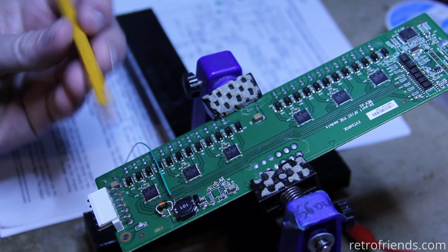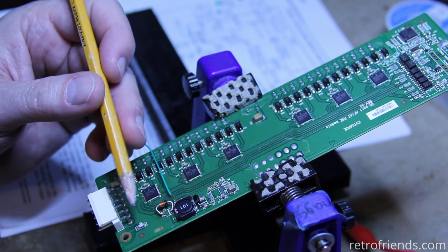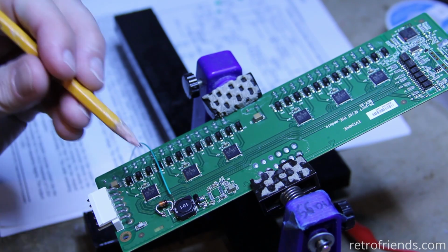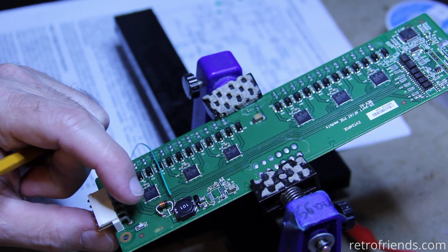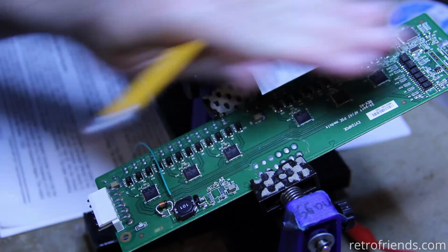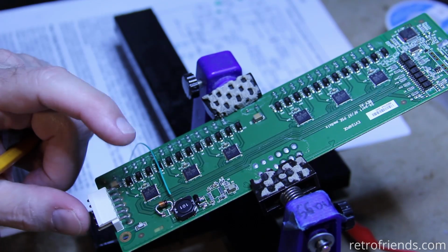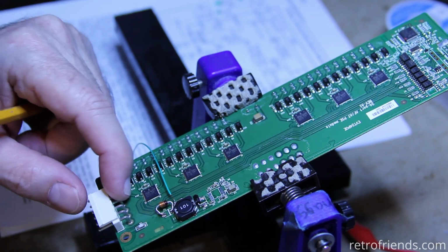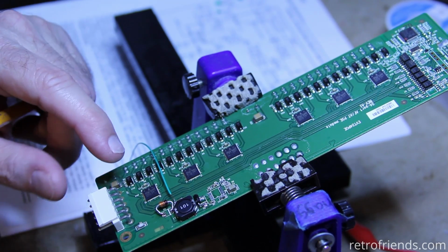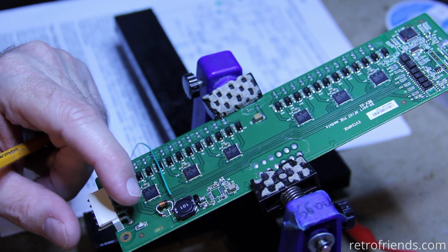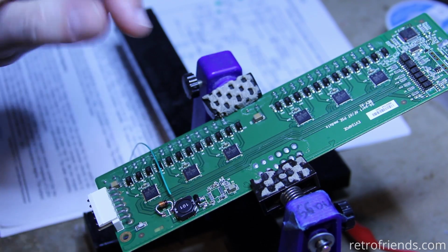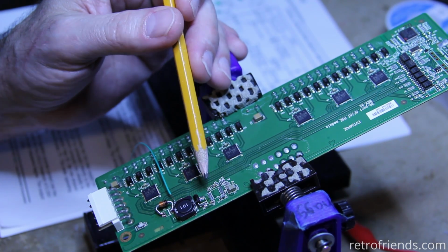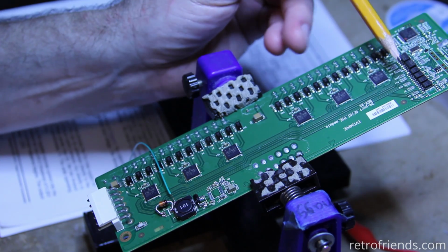So it's kind of easy to trace because everything for this circuit is on this side of the board. This is a multi-layer board. The 56 volts of DC has its own layer in there. There's also obviously a ground layer, but there's also ground planes on this side, plus I believe there's probably a ground layer for EMI or whatever. But there's a 56 volt layer, and there's also the 5 volt layer, because I don't see any traces coming from here on either side of the board, coming from here over to here.